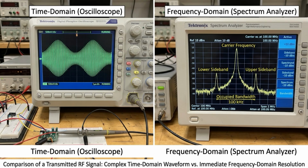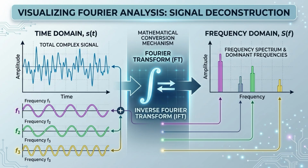Physically, a transmitted RF signal may appear as a rapidly oscillating waveform when observed on an oscilloscope. While the waveform itself may seem complicated, its frequency domain representation immediately shows the carrier frequency, sidebands, and bandwidth. Mathematically, every sufficiently well-behaved signal can be represented as a combination of sinusoidal components. Fourier analysis provides the mechanism for converting between the time domain and the frequency domain, allowing engineers to study signals